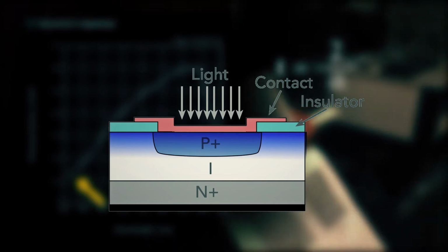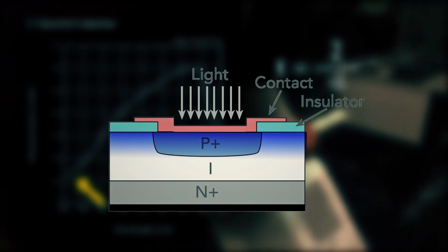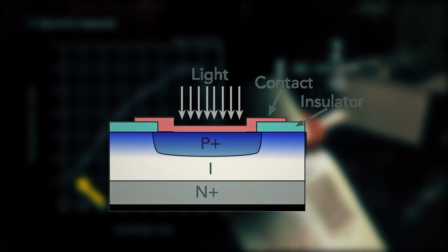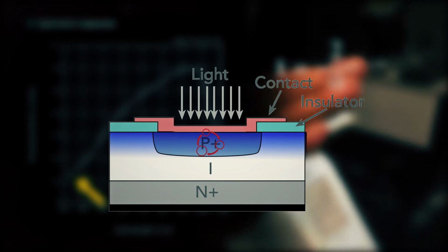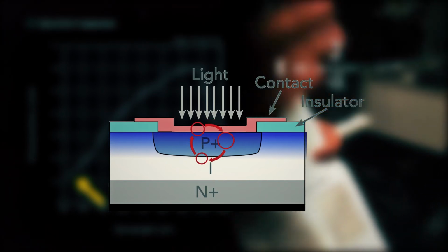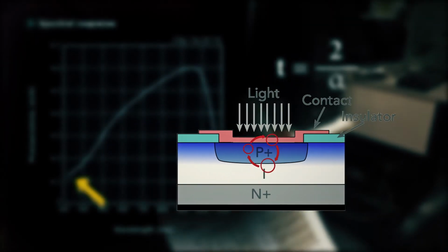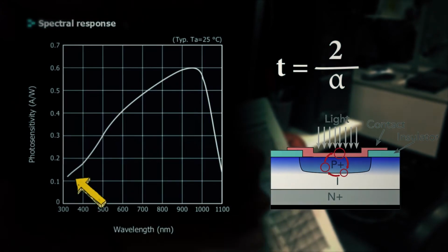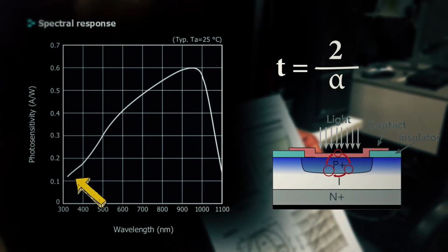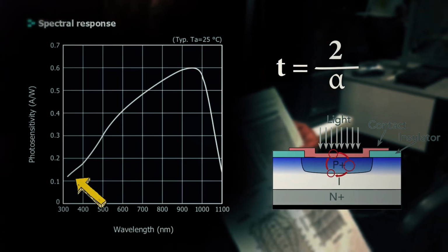With this, the radiation might be absorbed in the doped part of the surface of the device. Generating electron-hole pairs in the doped area leads to an instant recombination of the minority carriers, decreasing the response of the photodetector. So, the material is actually very absorbent in these wavelengths, but it happens very close to the surface in doped areas, reducing the response of the photodetector.